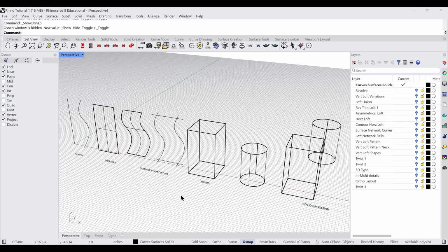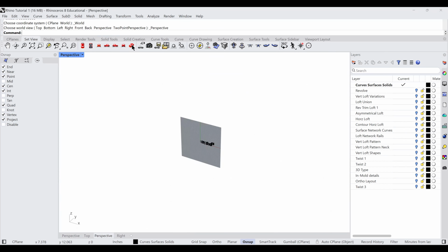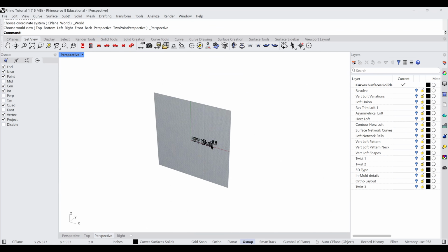So some of these commands work for the other views. So if I go to the front view and I right click and I'm rolling around, there is no panning and rotating. So it's just basically moving. So that would be it. Right click and then you move the ball around. And then of course we can go in and out with the wheel. So that'll take a little practice. Once you get that down, you'll be able to navigate very easily throughout all the different views. So I'm just going to click on the perspective view, and it's going to go back into that view.